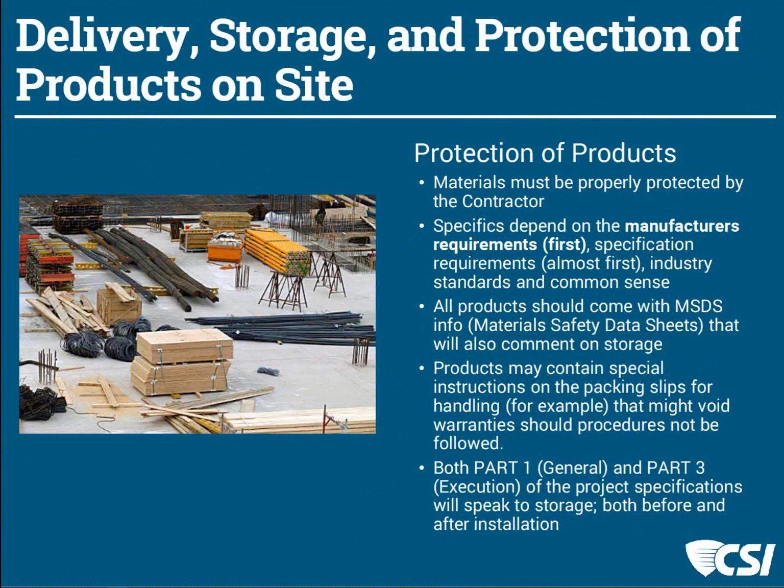Directly behind that and almost first is what our specifications say about the storage of a particular material, and then next would be whatever kind of industry standards and or common sense that come along with the storage of material. Products come with material safety data sheets that may speak to storage, or there may be other special instructions that come with the materials as they are shipped to the job.